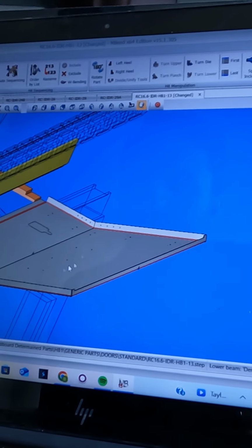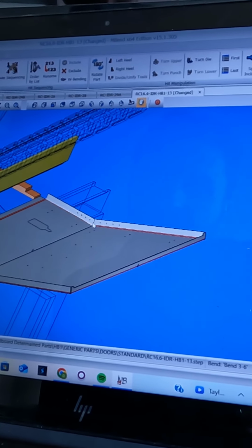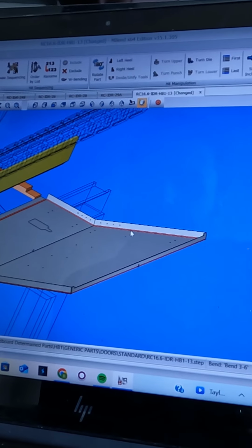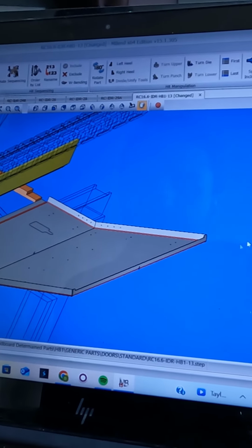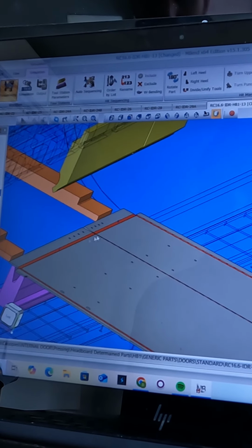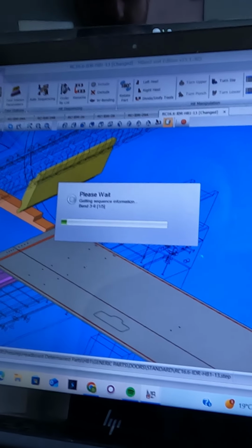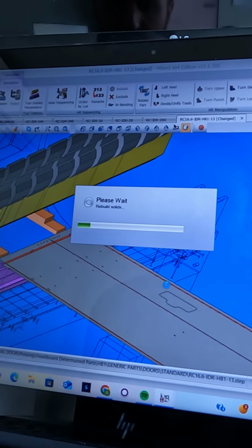As you can see here, if we were to press our 3 long edges first, it'd make it very hard to press our short edge. We'd have to press them as 2 separate parts. But because we pressed them first, back when it was a flat sheet, we're able to press both those folds all in one press.